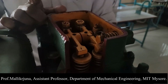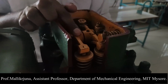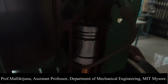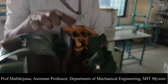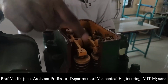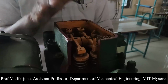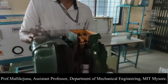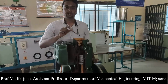Now if you clearly observe the inlet valve, please observe the inlet valve. Inlet valve is getting opened. Still the piston has not reached the TDC. That means the exhaust stroke has not completed. Before that, the inlet valve is getting opened. I am ready with one more reading now, which is nothing but inlet valve opening before the piston reaches the TDC. So this is the crank angle at which the inlet valve is getting opened. This is the reading that I can look at on the scale. Before the piston reaches the TDC, the inlet valve is getting opened.